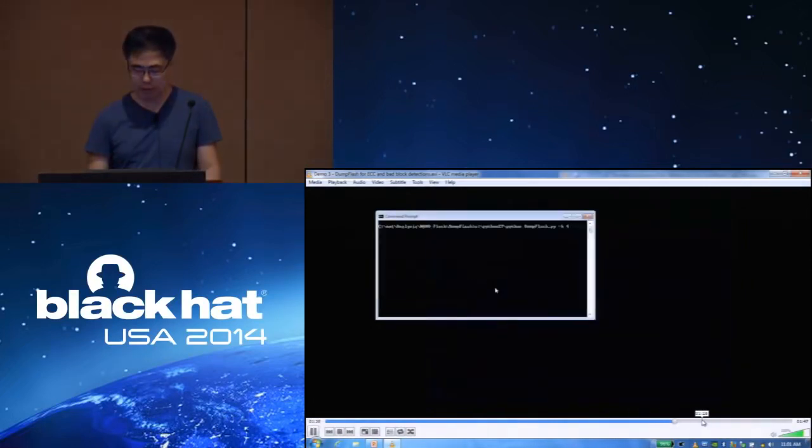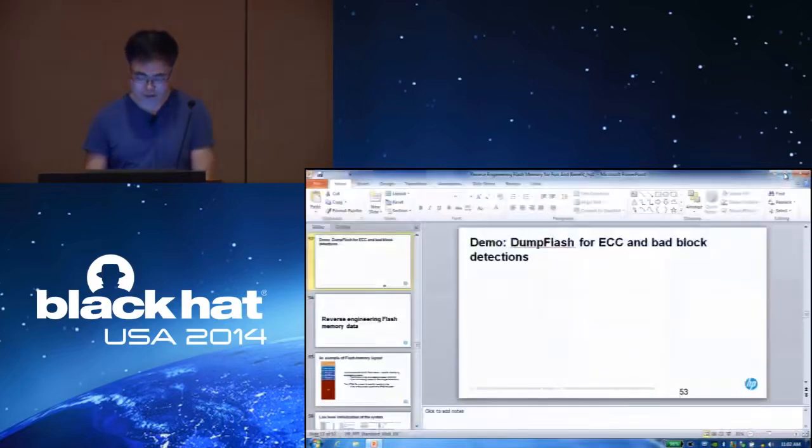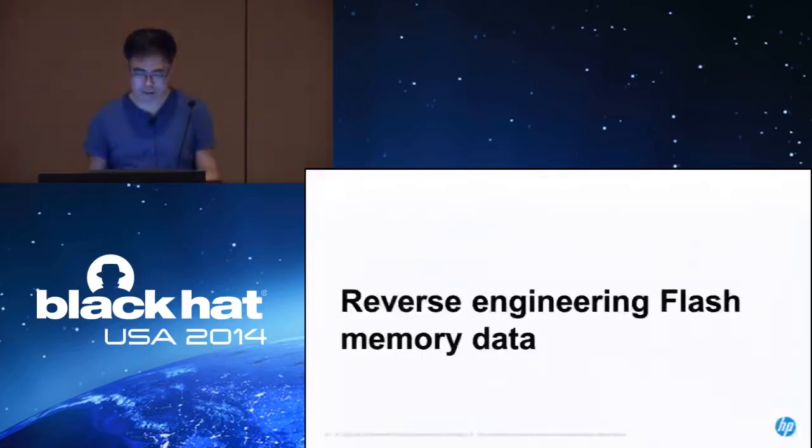So we skip, and you can pass the C option, it will check the ECCs. This operation is much slower because it's reading whole pages. For every page, it will read the whole page, and it is calculating ECC for every page. But usually you don't see ECC errors. I've never seen ECC errors from the chips I worked on. So this is it. Go next.